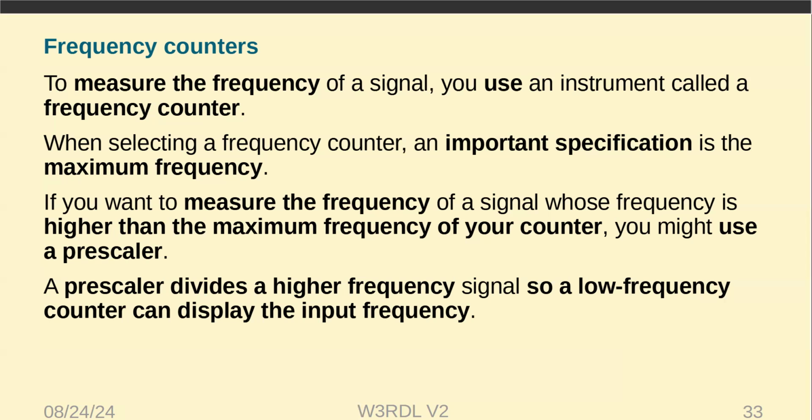Well, a frequency counter is going to have a hard time doing a measurement on a complex waveform. Normally, you would use it on something that's sinusoidal or a digital square wave type signal. If you've got a complex waveform, I'm not sure what kind of reading you're going to see. I wouldn't trust it. For something like that, you need to use an oscilloscope or look at the spectrum analyzer to see what the components are. Okay, thank you.